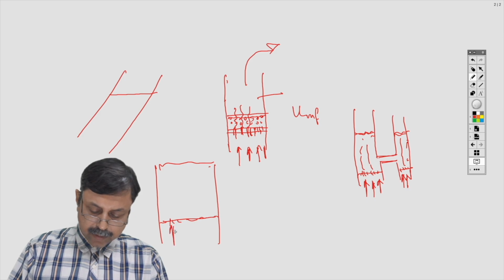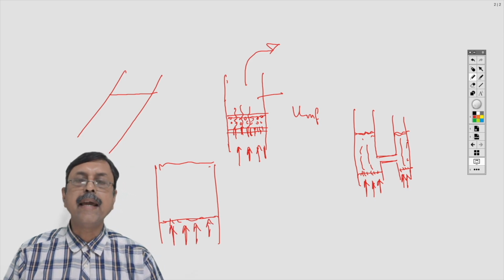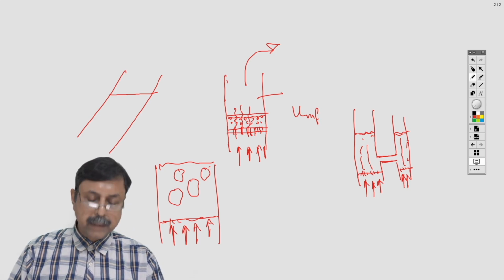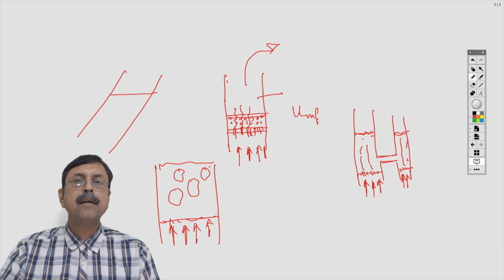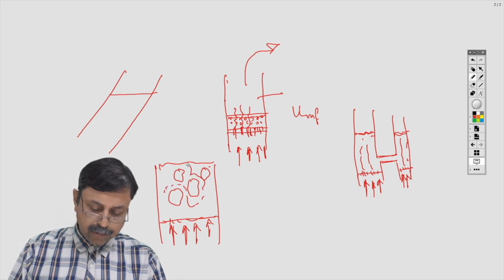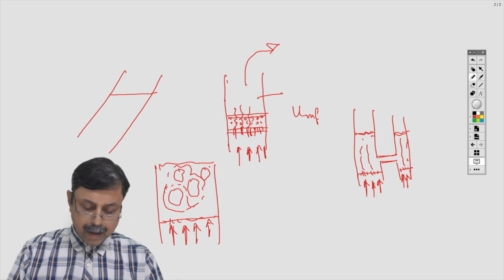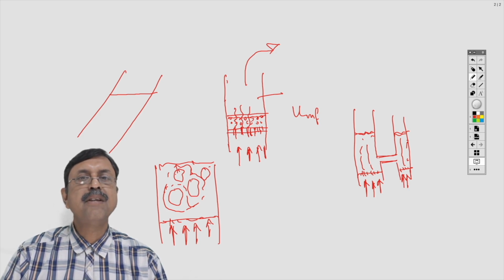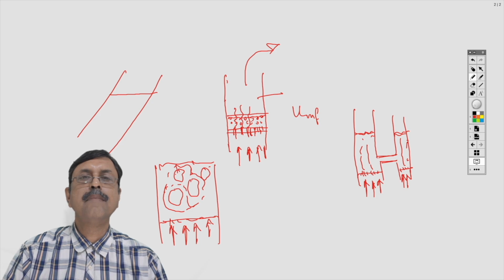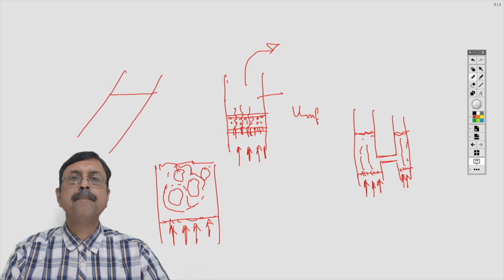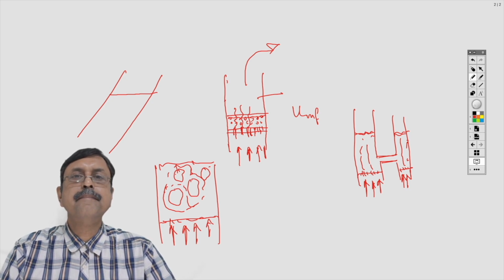And also, if there is a bed and if the fluid flow is very high, then the fluid may create some kind of bubble inside the bed. That means there will be a bubble where there will be no solid inside, and all the solids will be outside the bubble. And this bubble will burst when it comes to the surface of the fluidized bed, just like it happens for a liquid. So the fluidized bed will have all the liquid-like properties, and that's why it is called fluidization.